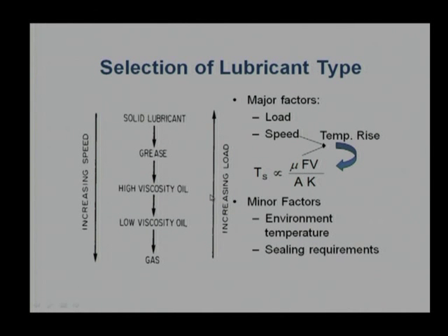So, it is slightly complex. More load, we should choose a semi solid and solids, but that is going to increase the temperature. If the increase in temperature is reducing the viscosity of the lubricant, then we should choose some sort of additives, and this indicates that a study of the additives along with this kind of lubricant is essential.